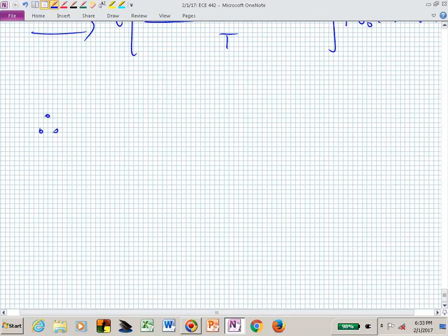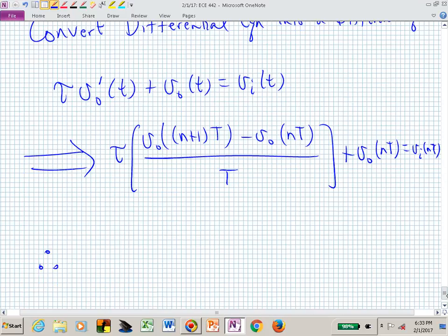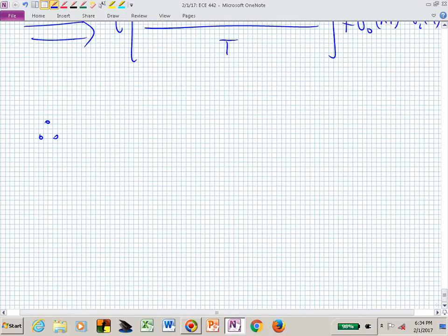They may sort of cancel out, but our bandwidth is not exactly 100 hertz. It's still approximately 100 hertz. If we carried the 2 pi through, it would have just meant that our resistors and capacitors would have had weird numbers relative to the bandwidth of our filter. So it doesn't really matter. We're just making that approximation consistently throughout, but I'm not sure that they really cancel each other out.